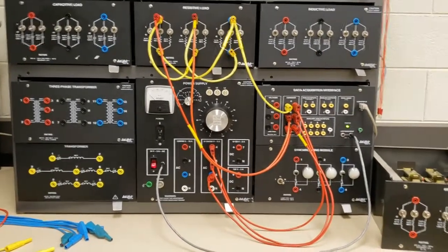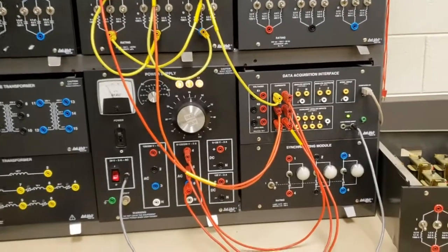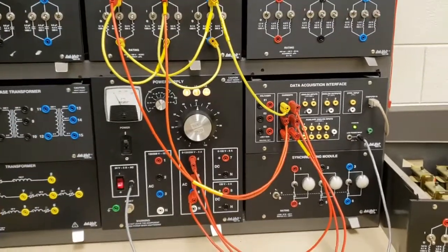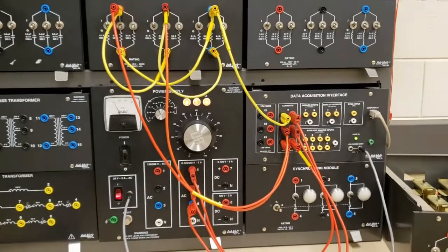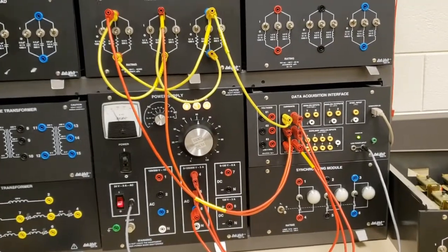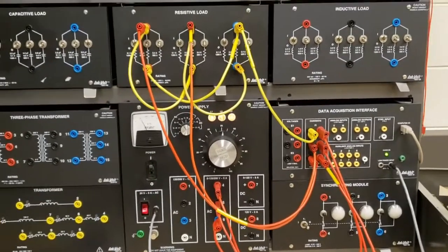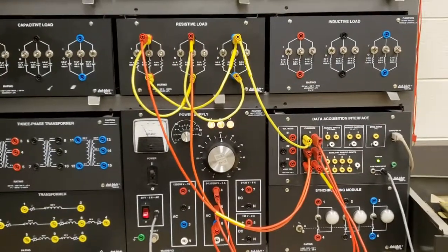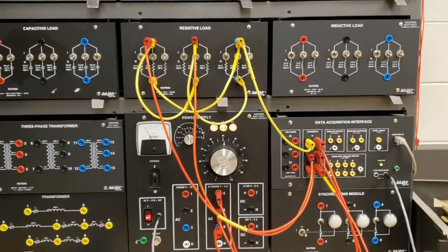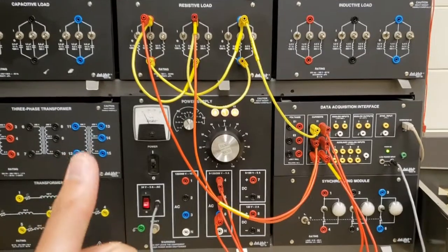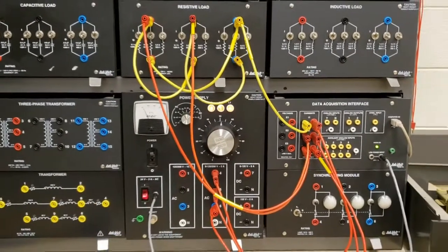Okay, so I'm going to go ahead and test that out. I'll just pause the video for a second. All right, so I have the computer configured. It's measuring the currents going through. I removed all the voltage measurements because we don't need that anymore. So I'm just measuring the current going into the load. If this is correctly put up, we should see, first, that the currents are 3-phase, as in equal magnitude, 120 degrees apart.